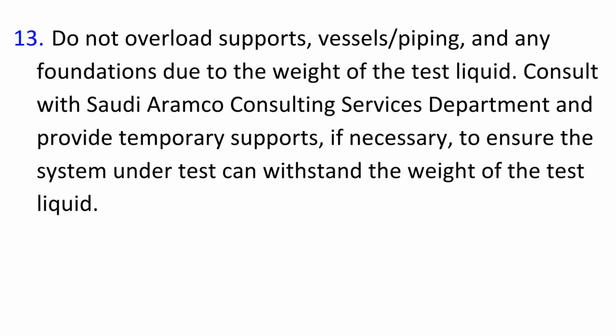13. Do not overload supports, vessels, piping, and any foundations due to the weight of the test liquid. Consult with Saudi Aramco Consulting Services Department and provide temporary supports, if necessary, to ensure the system under test can withstand the weight of the test liquid.